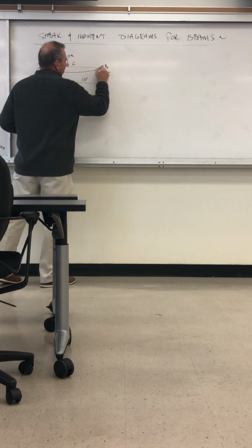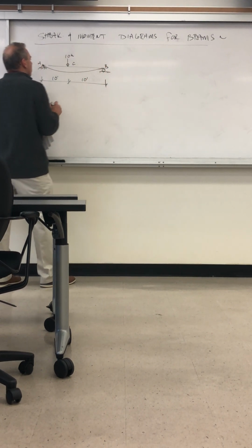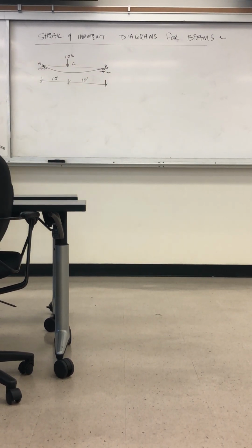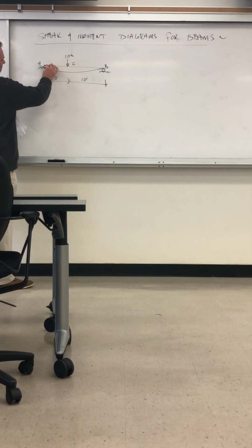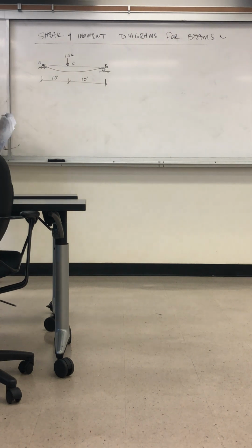This is greatly exaggerated, but that's the display shape. There's zero vertical displacement at the end supports. There's rotation here because the two ends cannot hold a moment. So we know ahead of time that the bending moments are going to be zero.